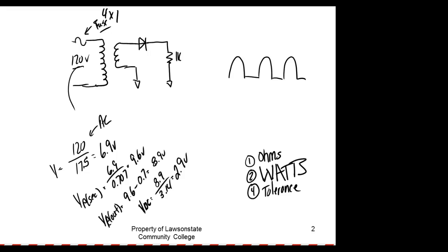But now I'm fixing to fire this puppy up, and I got to see if I'm gonna burn this up. Right? You understand? So what would be the wattage rating on that? Well, we know our voltage is around 3 volts, so 3 squared divided by 1K, right? So 3 squared divided by 1,000 is 9 milliwatts. I got a quarter watt resistor, so I'm fine. So we're okay. So let's measure our voltage and see what we got. We're expecting around 3 volts, and we'll see if we got it.